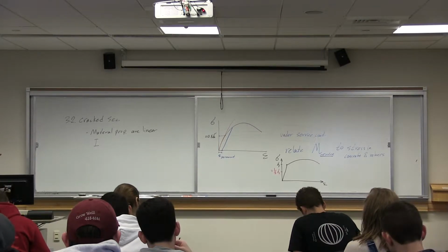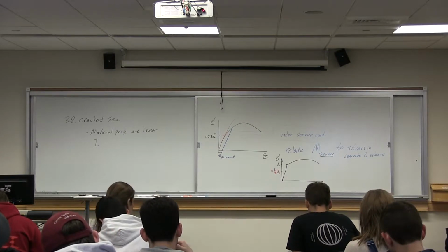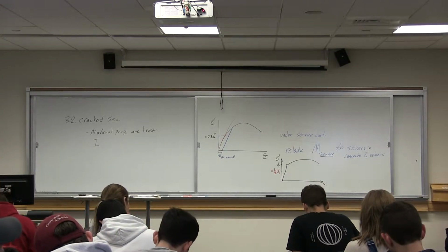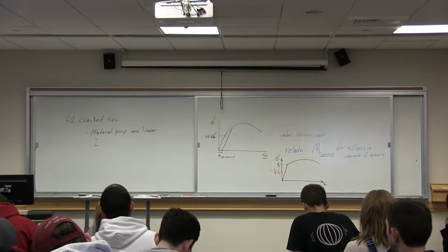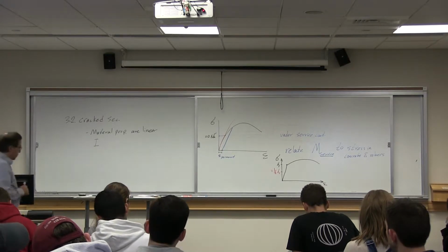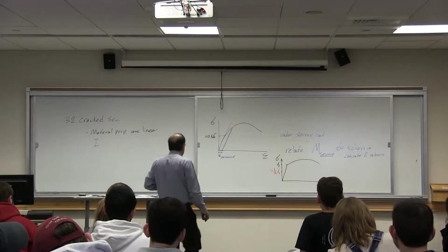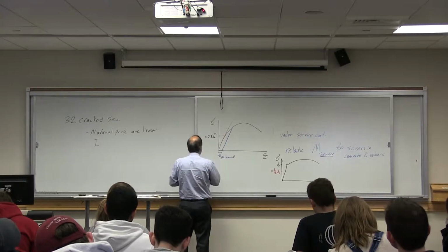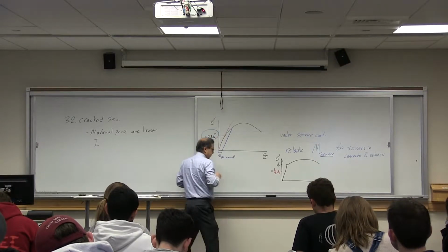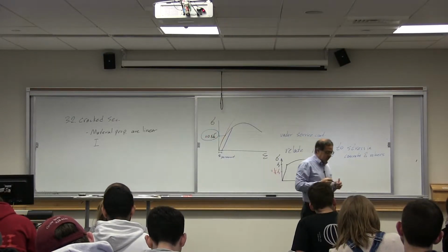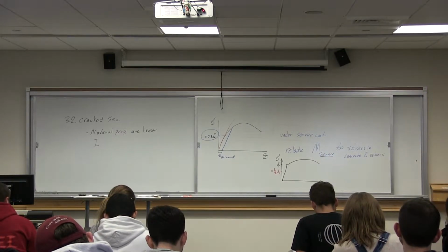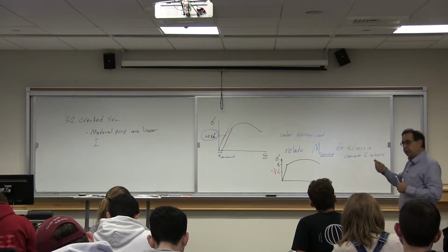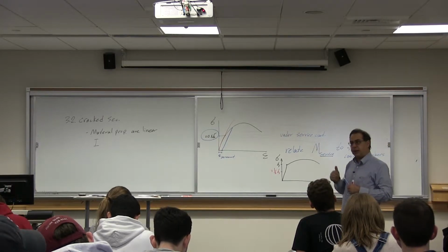This 1/2 of Fy obviously is less than Fy, which is a good thing. We said we don't want to go over Fy, we still don't go, we make it smaller. To summarize, if we limit the concrete compressive stress to about 1/2 of F prime C, we will expect a good behavior from concrete in compression.